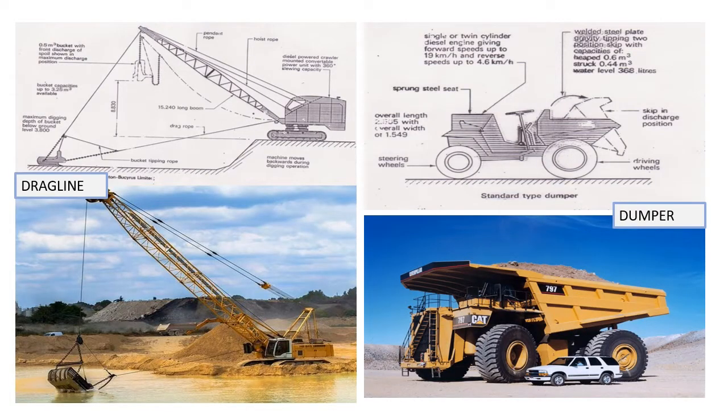Next is dragline. These machines are based on universal power unit with a basic crane rigging to which is attached a drag bucket. The machine is primarily designed for bulk excavation in loose soils up to 3,000 mm below its own track level by swinging the bucket out to the excavation position and hauling or dragging it back towards the power unit. Dragline machines can also be fitted with a grab or clamshell bucket for excavating in very loose soils.